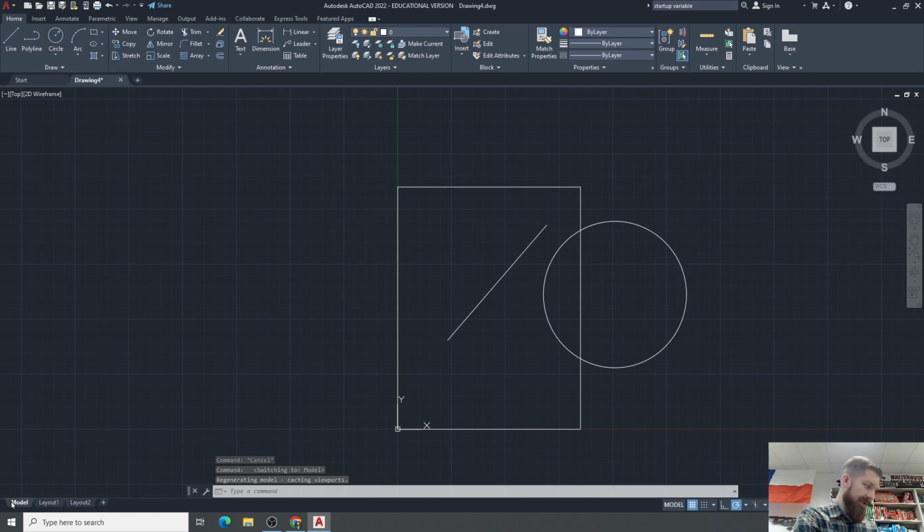All right, helpful hint. Before beginning to create an AutoCAD drawing, determine the size of the drawing area needed for the intended geometry. You always want to draw the stuff one-to-one, right? Don't try to scale it on your own. Just draw it the size that it's going to be. After setting units, which we talked about, appropriate limits should be set in order to draw the objects to the real-world size in actual units, 1-to-1 scale.